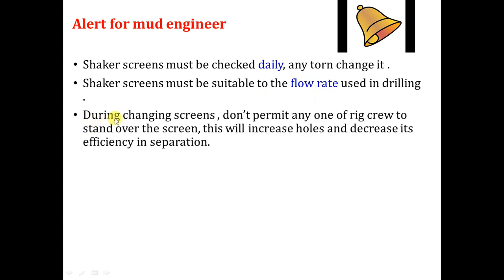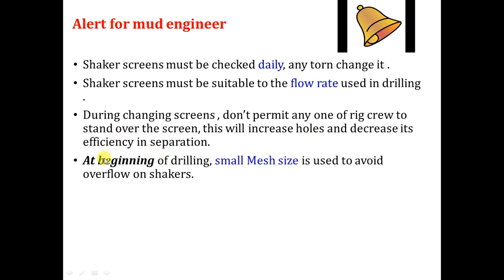Number three, during changing the screens, don't permit anybody on the rig floor or on the rig crew to stand over the screen. Why? Because this will increase the holes, or the apertures, for example, and decrease its efficiency in separation.